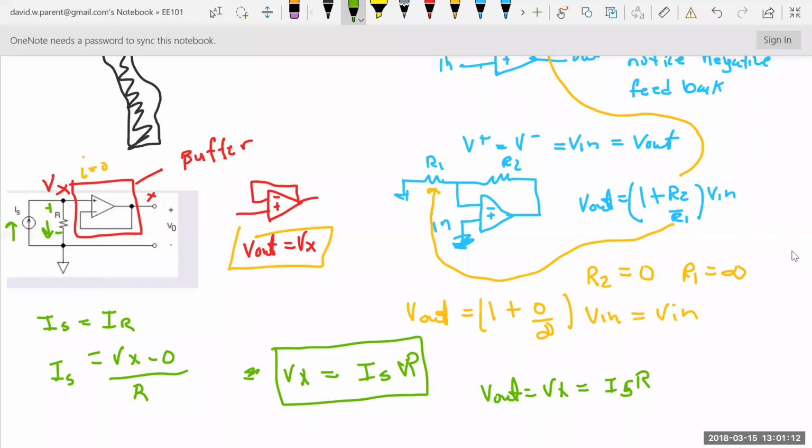So the cool thing about this problem from a teaching perspective is that it tests whether you get that this is a non-inverting amplifier. It tests that you know no current flows in here. And then in a more complex way, do you know V equals IR? Because we have current, right? So what is voltage? Current times resistance, which, yeah, we called it nodal analysis, but that's all we were looking for, right?